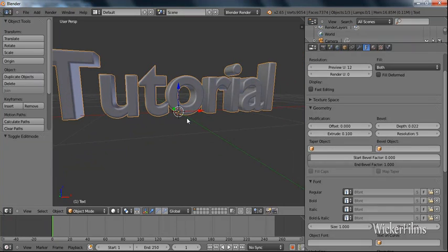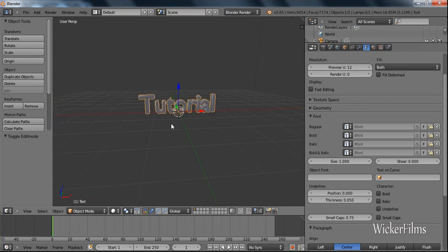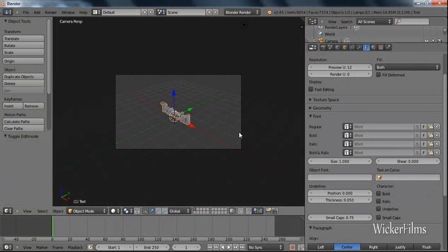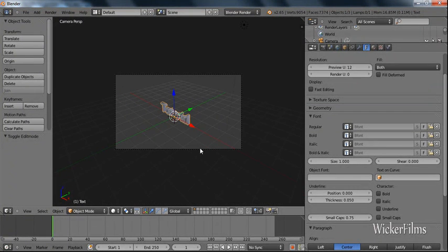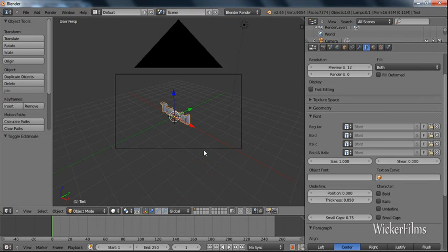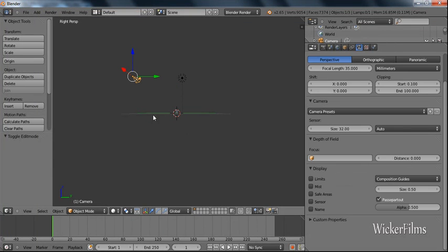Okay, that's all right. Now after I'm done here, I just want to do a couple of things. As you see, this is how it looks, and you don't want your render file to be in that kind of position. So I'm going to go to side view, select the camera, and click Alt and R so that we can reset the rotation.